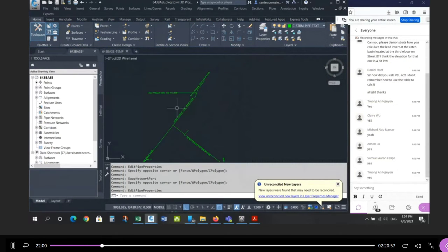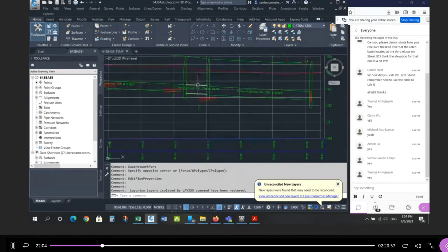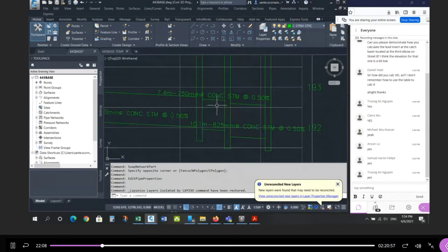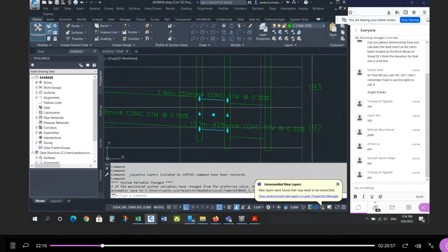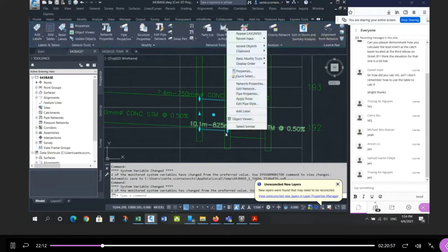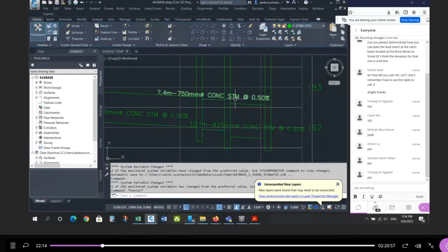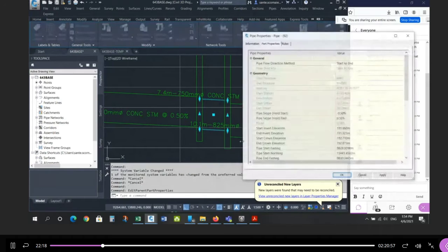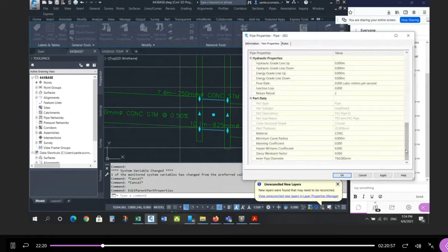So once you change the pipe size, and you have access to that in the profile, you can actually do that in the profile. If we go to Street A, I can actually change the pipe size here. I can use the swap command if it works. It doesn't always work. Actually, it might not be here. The swap command's not here. But you can go to the pipe property and change the size here, as long as you're just accessing the database.